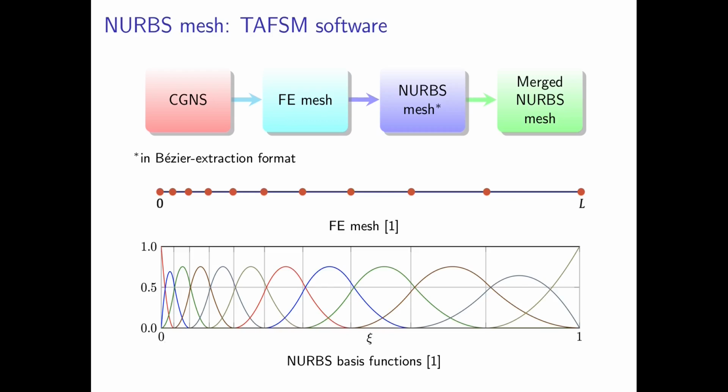The final step in this scheme merges the control points over a shared surface between two adjacent blocks. It's a very important step because it ensures that the projections result in the same control point positions. And this leads to C0 continuity for the basis function across the surface.